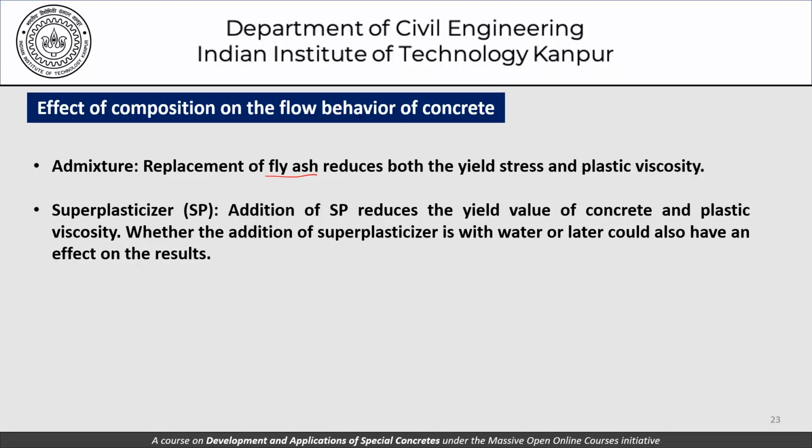However, whether the superplasticizer is added with water or later could also have an effect on the results. What this sentence means is that whether the plasticizer is added to concrete with water at the time of mixing as a single shot, or used in stages, would possibly also be an important factor when it comes to the reduction in the yield value and plastic viscosity.